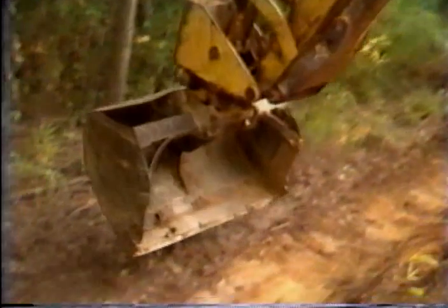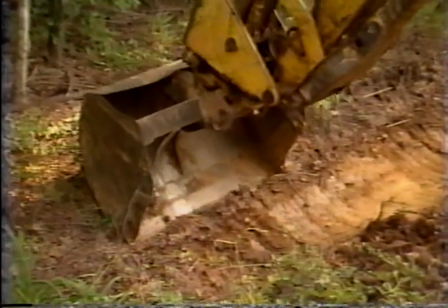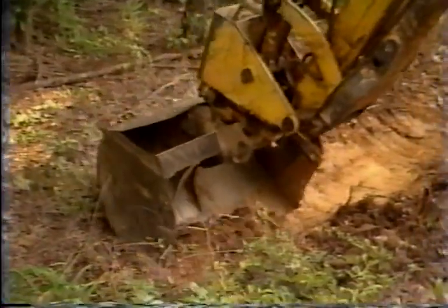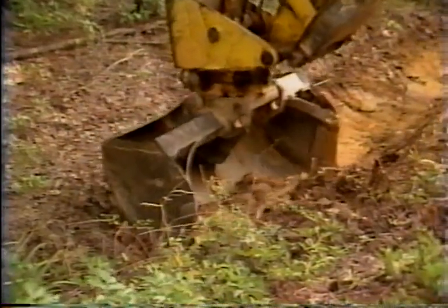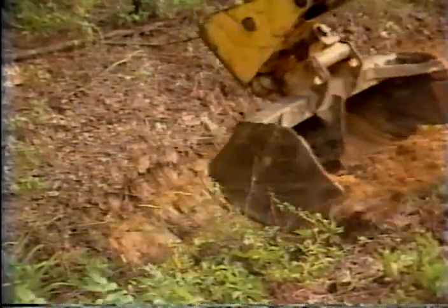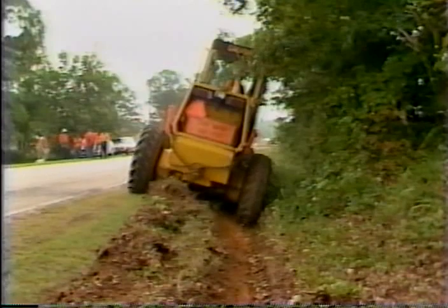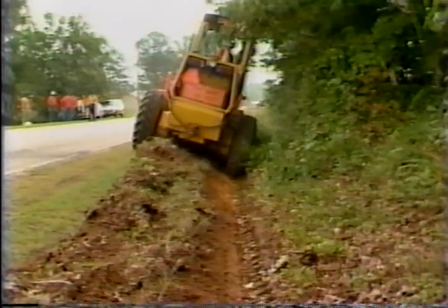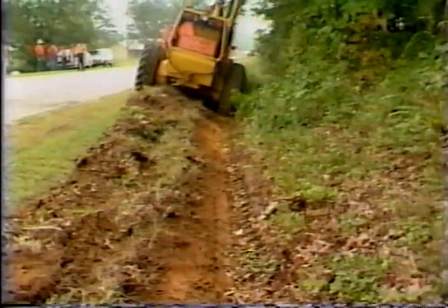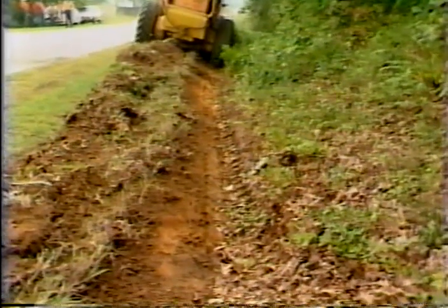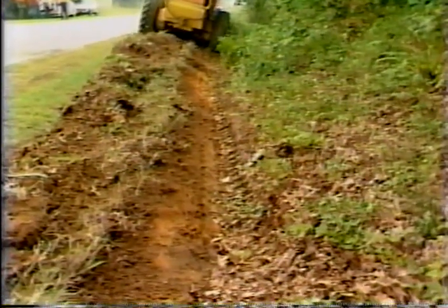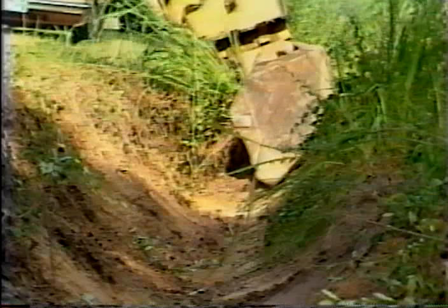Remember the 3 basic goals that are accomplished by performing proper ditch maintenance. The first is cleaning out the ditch. Remove dirt, debris, and other such materials. The second is proper reshaping of the ditch. Reshape the ditch to its original cross-section. This should be a well-groomed, smooth V or U-shaped section.